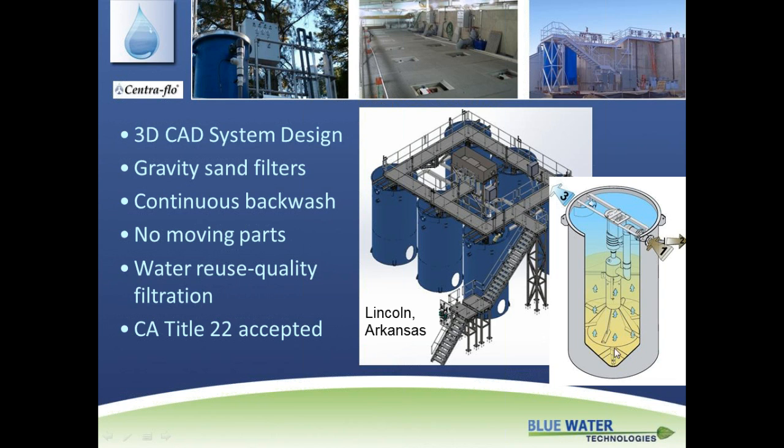And through the scrubbing action that you get with that airlift, you get a very high energy scrub that'll completely strip an old coating of what we use to absorb these metals, and that'll remove it from the process, putting clean media back to the top of the bed.